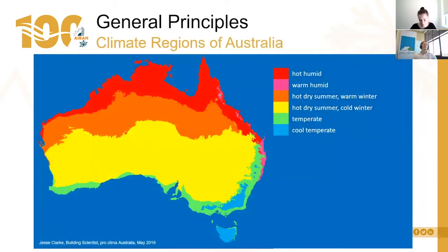Next, please. One of the key things that we all know as members of AIRAH is that when you're in different climates, you need different heating and different cooling strategies, with potentially different humidification or dehumidification systems. In hot humid climates, there are far different requirements and different problems, when you've got all the external moisture, compared to the cool temperate or alpine regions, where you potentially have a lot of moisture inside the building and very cold conditions outside the building. So the design of the building fabric that works with the HVAC systems is critically important in all those climates.